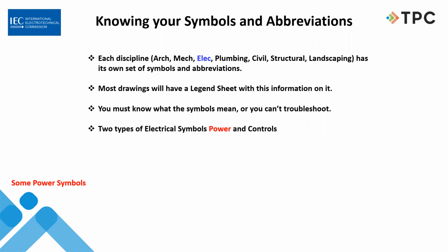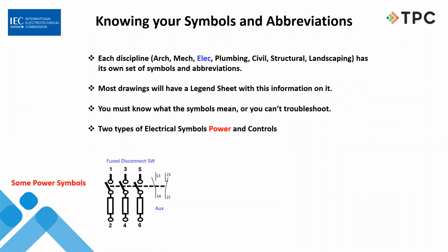So let's talk about some power symbols that we're going to see on drawings. And these are all IEC drawings. This is a three-phase fuse disconnect switch. Now, I've seen several different drawings of this particular switch, and some show the fuses on the angled lines and some show them below. So it really depends on the manufacturer of your equipment.